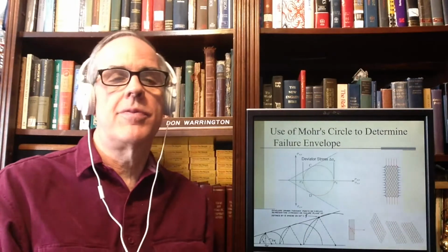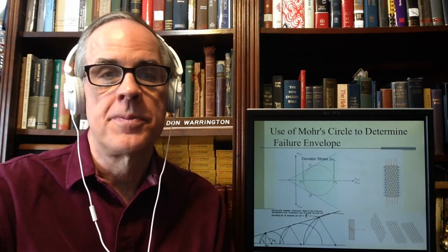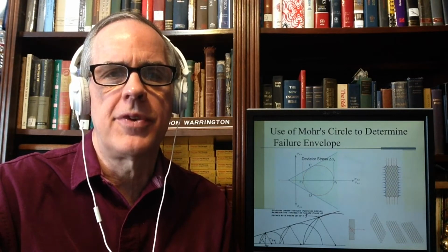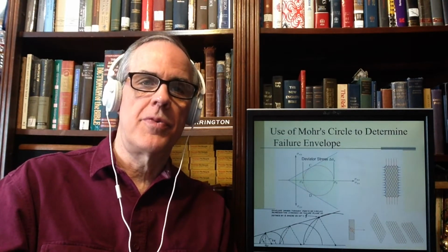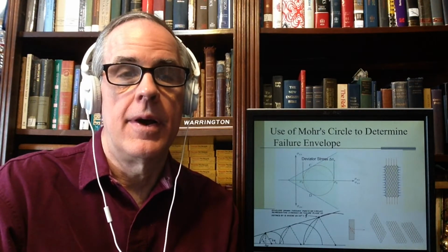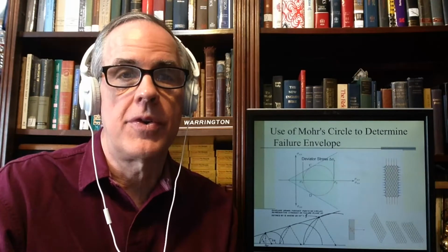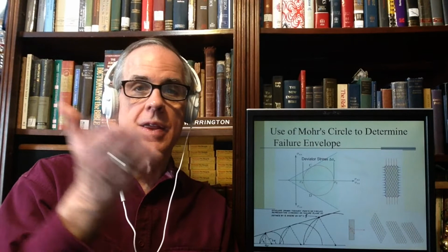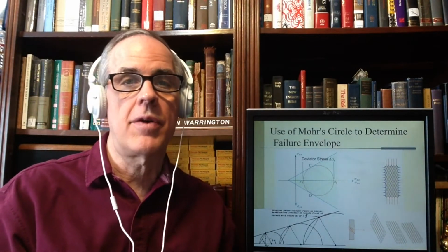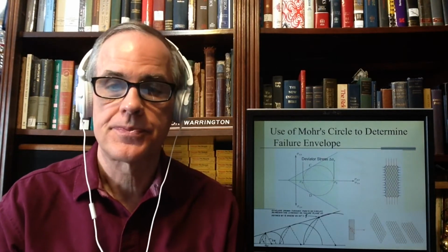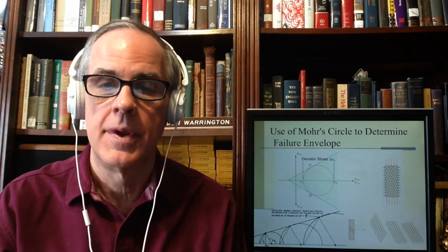If you recall, again, from Mohr's circle, I'm being repetitious on this, your underlying assumption in a triaxial test is your first principal stress is this way, and your third one is your confining stress this way. Well, if it follows maximum shear stress theory or Mohr Coulomb, then that means that the failure surface is 45 degrees out, because on Mohr's circle, the maximum shear stress point is 90 degrees out. So you get that failure very often.